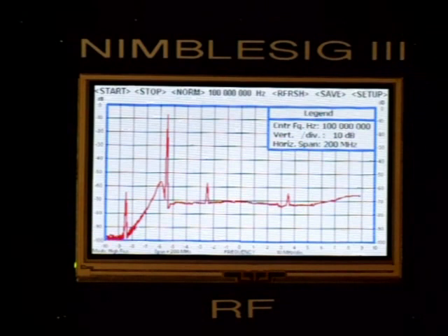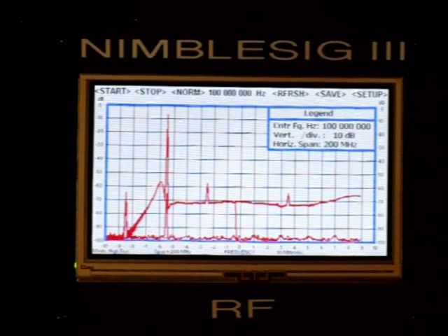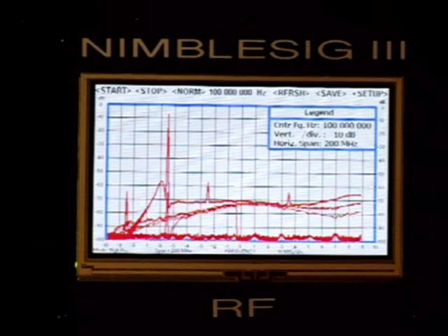This generator has the capability to subtract out any frequency response variations in the test bed and in the instrumentation. To do that, what I must first of all do is take the crystal filter out of the circuit. I've got it disconnected now, and what you're looking at on the bottom there is the noise floor of the test set. I'm now connecting back up to the mixer.